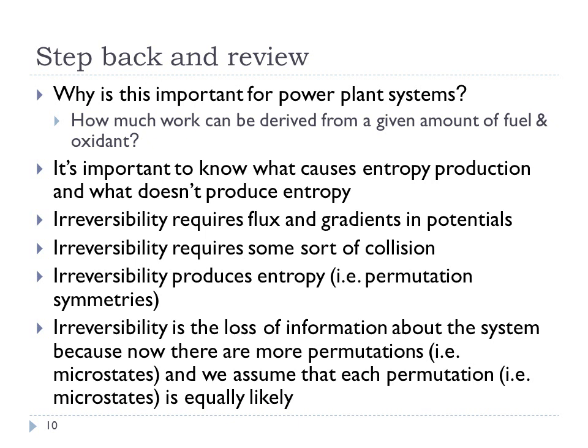So one way of increasing the amount of power from a power plant can often be to increase the size of heat exchangers. But what you find is then the capital cost goes up, and there's going to be some optimum. When you design heat exchangers, you'll find that there's actually an optimum area for the heat exchanger, such that if you were to shrink the area, what you'd find is that your power production would start dropping. So your capital costs would drop, but your power production would drop more in equivalent terms.